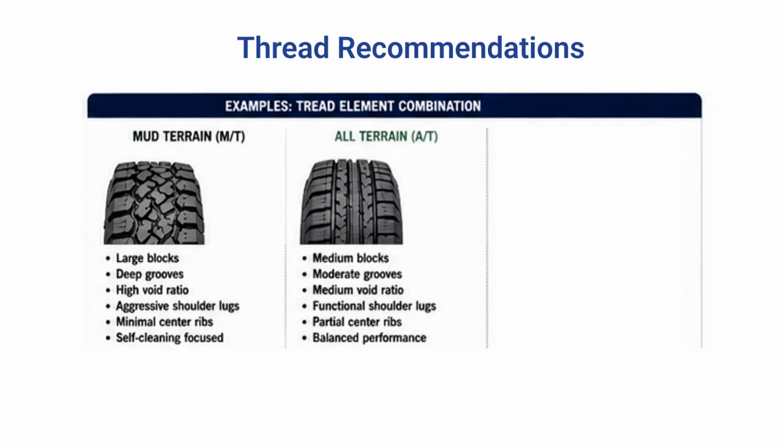Next is the all-terrain tyre, or AT. It combines medium-sized blocks, moderate grooves, and a medium void ratio. Functional shoulder lugs and partial center ribs provide a balance between off-road traction and on-road stability. This makes it suitable for mixed terrain, gravel, hard soil, and military patrol routes.